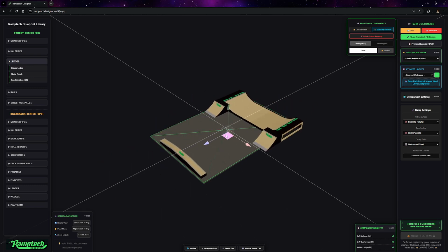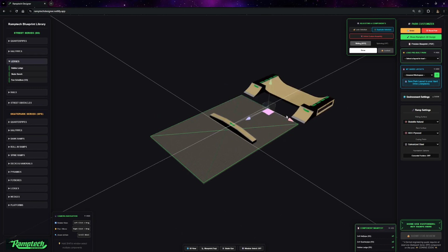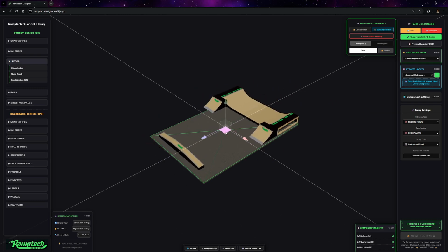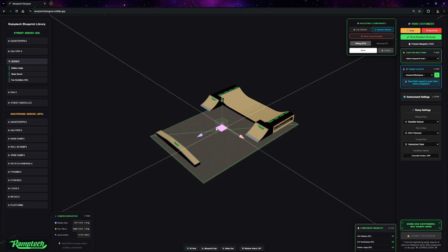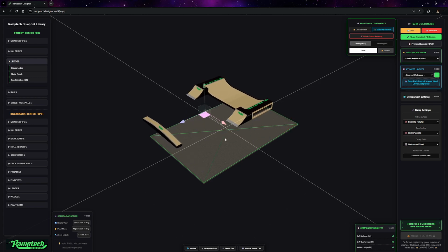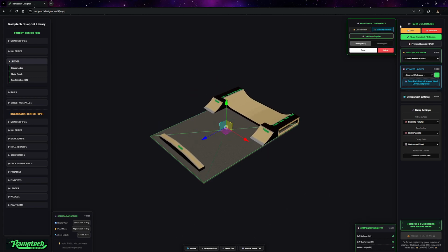Now, you remember what I said about the gizmo not allowing you to drop ramps off the pad? That only really works when you're dealing with one ramp. Technically, you can slide them off the pad by grouping them, because the gizmo is going to center, and it's the gizmo that will not exit the pad. Let's unlink those. Let's go over here into our right UI.